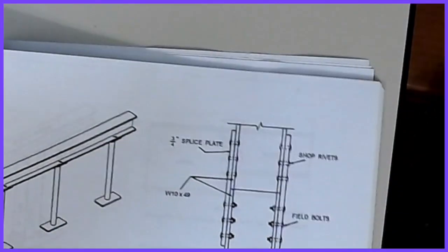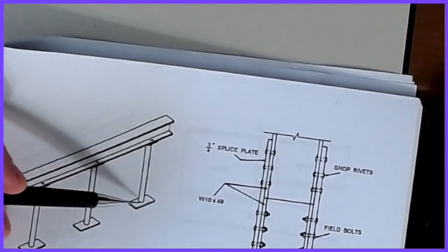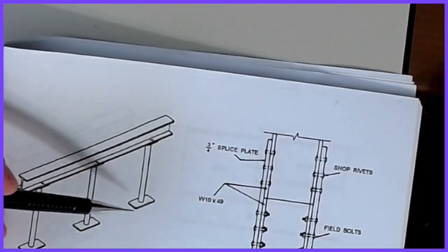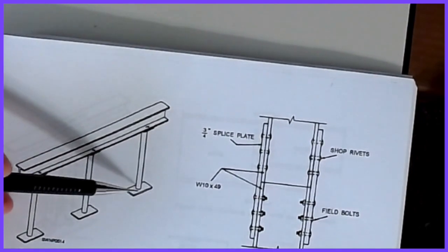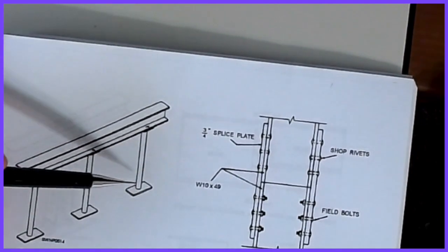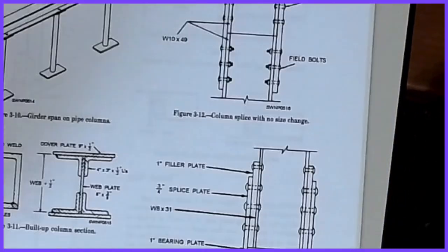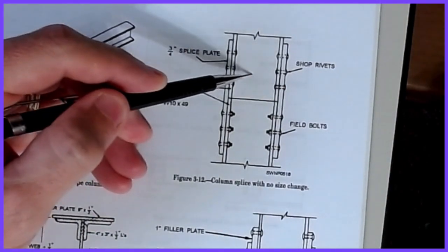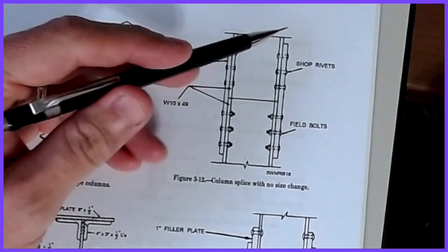Once you have your columns, you'll notice that depending on how tall your building is, they have certain lengths. If our story height is 12 to 15 feet, a column can generally ship in lengths as much as 40 feet before it gets too spindly. And so about every 2.5 floors is about the maximum length you can go on a normal column. So we have to start figuring out, how do I connect one column on the bottom to a column that continues up?